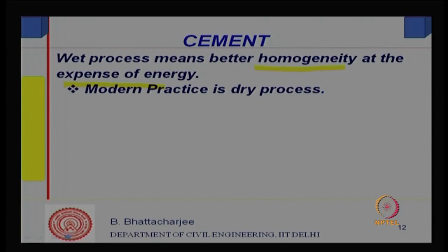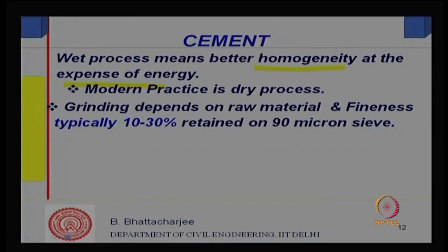Essentially what you have to do is mix lime and silica, or limestone and clay, in appropriate proportion, and grind them to fine size. The amount of grinding will of course depend upon the raw material. Generally it is ground until 10 to 30% is retained on a 90 micron sieve.